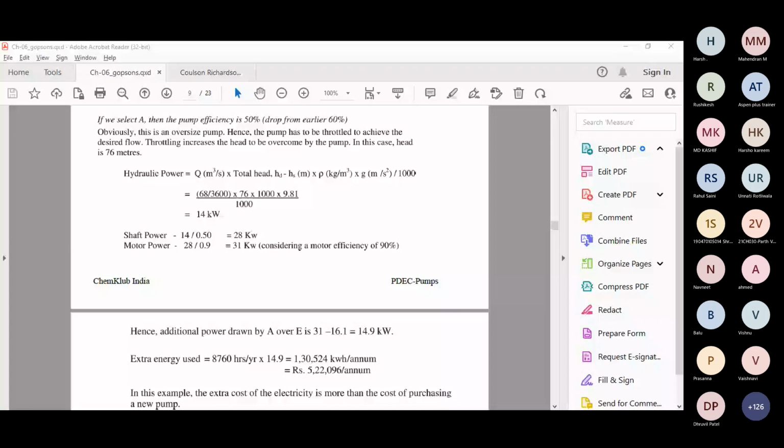So my pump is already designed for a good amount of NPSH. It is a low NPSH pump. It is already designed for 260 degree centigrade. I have already given it the data. It is not that I gave the data for operating at 50 and now I am operating at 250. Hot oil pumps are always designed somewhere between 250 and 350. Hot oils always have low vapor pressure.